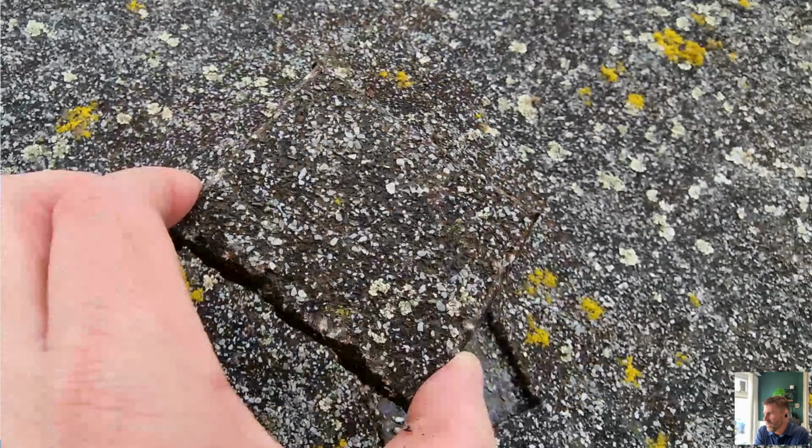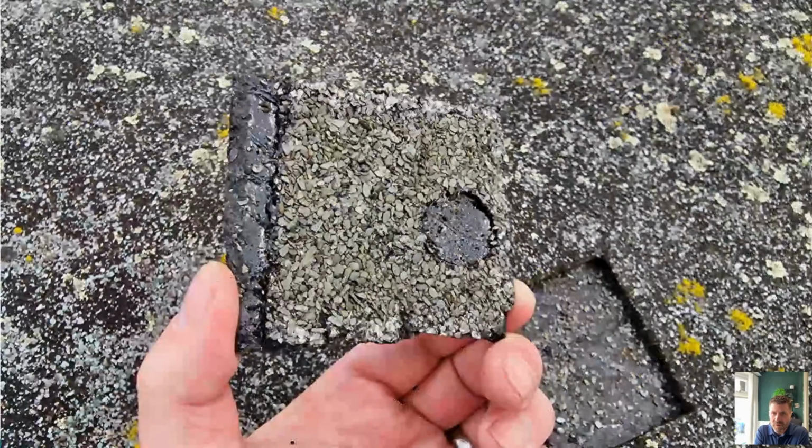So a bit of a progressive one here. This is an aged felt, as you can see there, likely a polyester oxidized felt system. We know it's a pour and roll system, because, like I say, we've gone through it on the previous ones, but we see the bitumen bead there and that the laps have been watered.